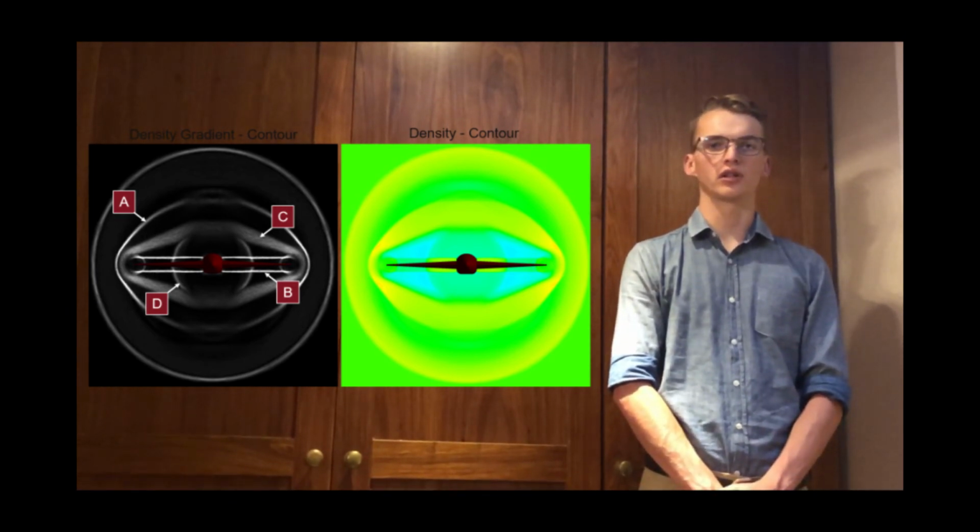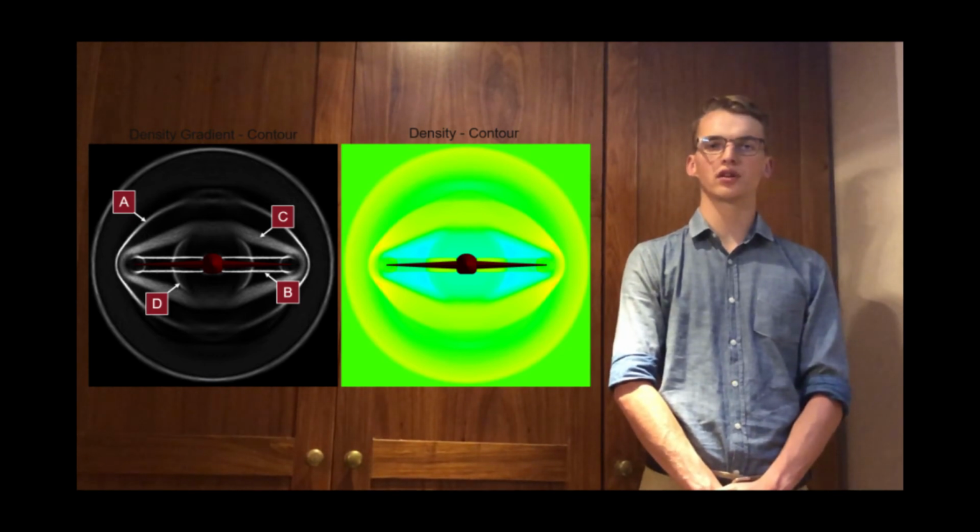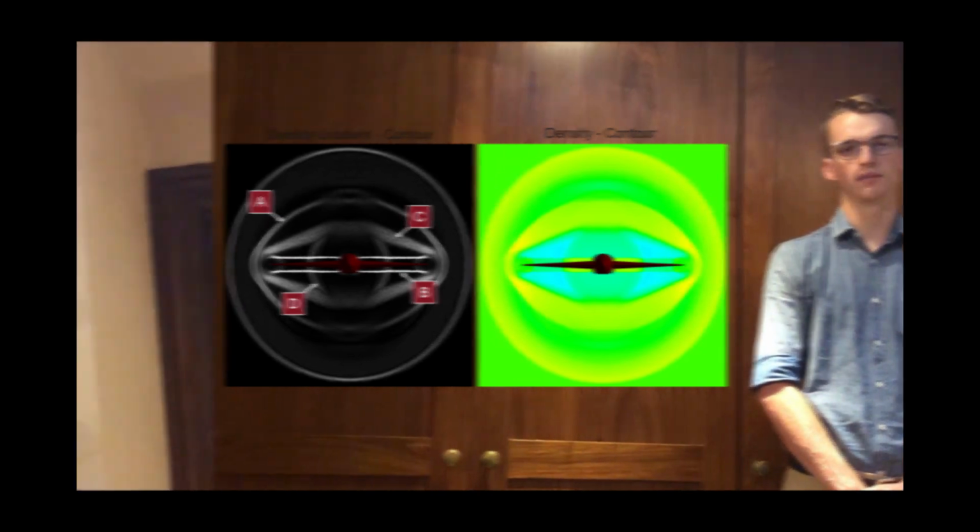The wing is not producing lift, so there are no tip vortices. If present, however, these would likely interact with these structures. Also of interest is the circular shock I was referring to earlier, marked by the point D.